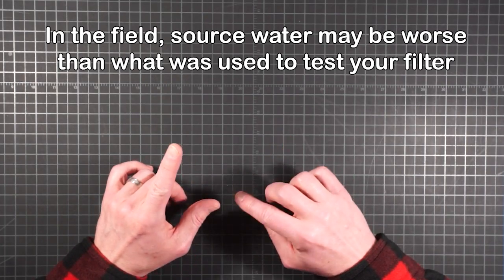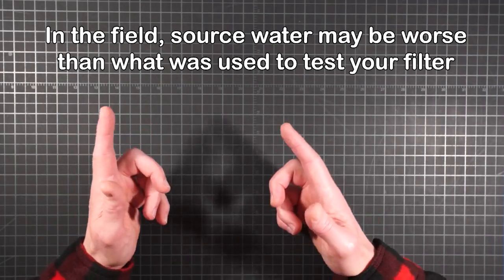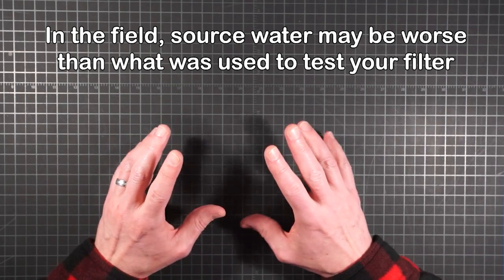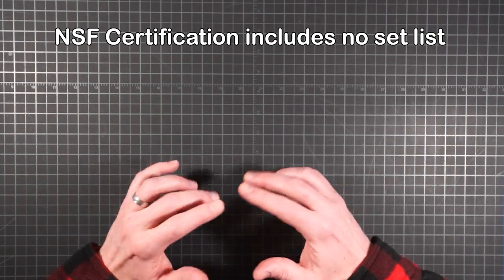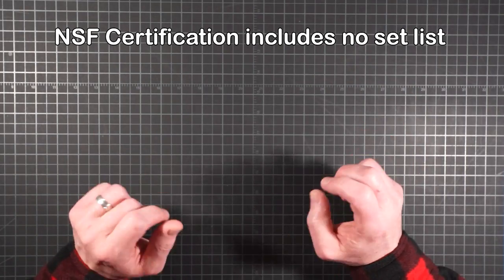But in the field, there's no rule governing the limit of what you might experience in your source water, so it's important to realize that all you really get from certification is a reduction amount, not a promise of water to any particular safety level. The other thing to bear in mind about claims of meeting NSF standards is there is no set list of substances that need to be reduced for certification.